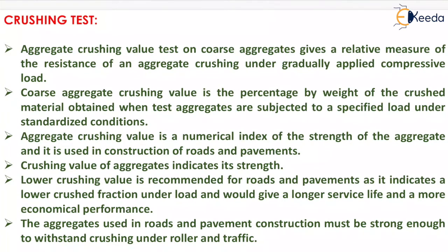Aggregate crushing value is a numerical index of the strength of the aggregate and it is used in construction of roads and pavements. Crushing value of aggregate indicates its strength. Lower crushing value is recommended for roads and pavements as it indicates a lower crushed fraction under load and would give a longer service life and a more economical performance.